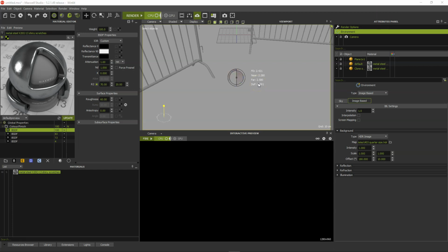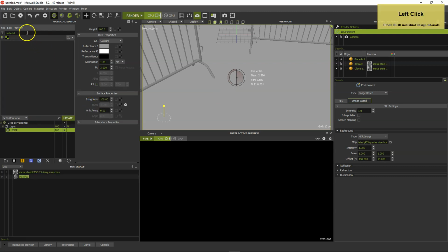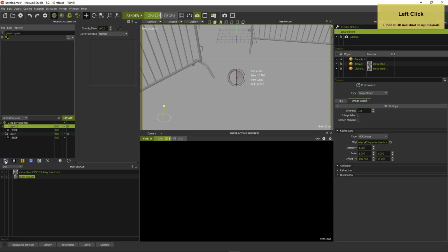Now that we have a suitable scene, camera and lighting, right-click in the Materials list and select New Custom. Rename the material, add a layer and rename both Blades and Ground. The blade texture must be in UV channel 0 and the ground texture in channel 1. I'm putting this in the layers names just as a reminder for beginners.